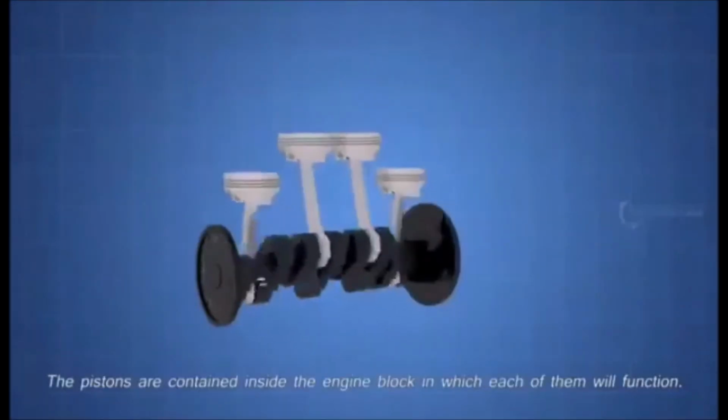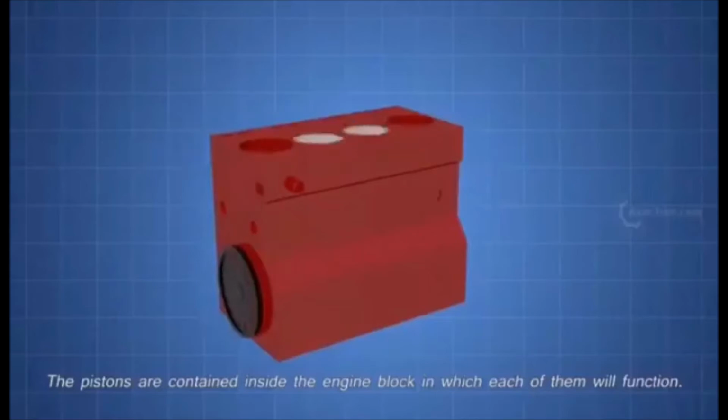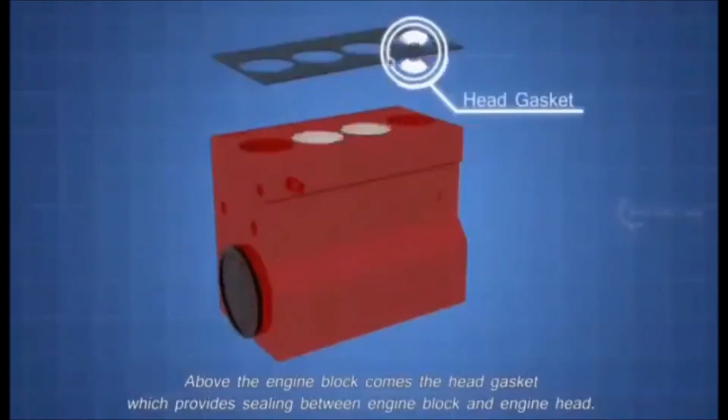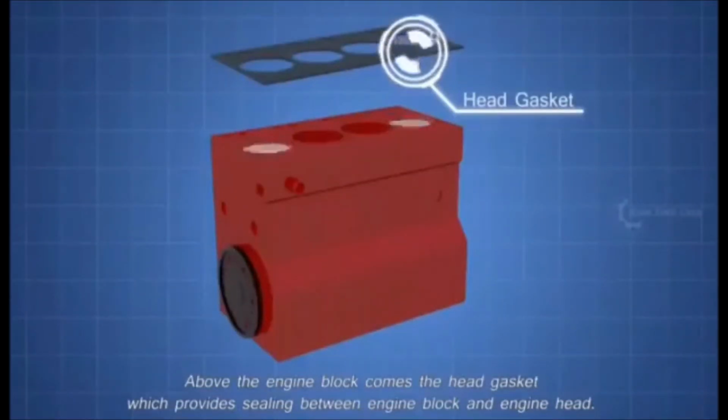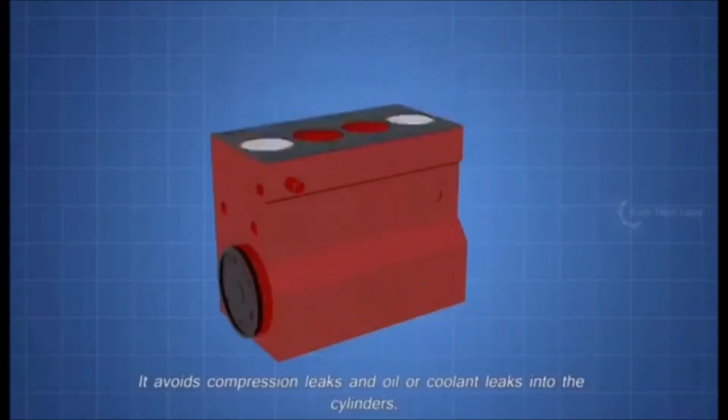These are the main parts involved in an engine cooling system. Now, let's see how these parts work together. The pistons are contained inside the engine block, in which each of them will function. Above the engine block comes the head gasket, which provides sealing between engine block and engine head. It avoids compression leaks, and oil or coolant leaks into the cylinders.